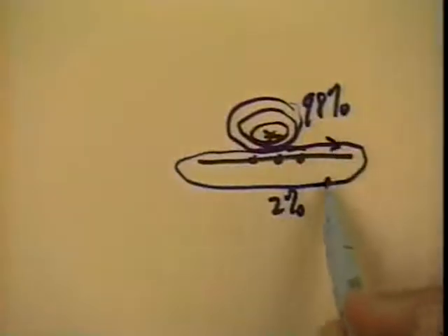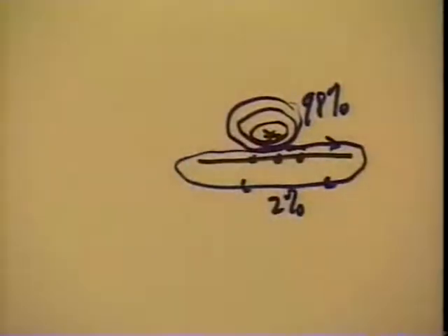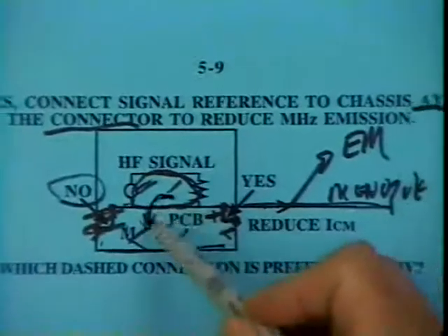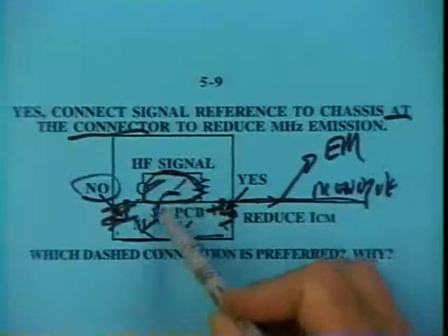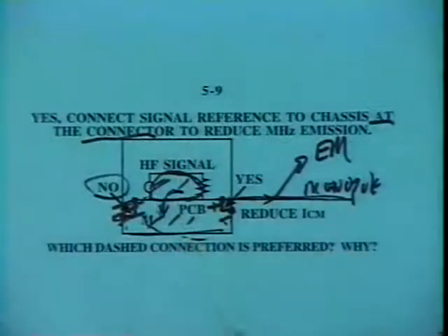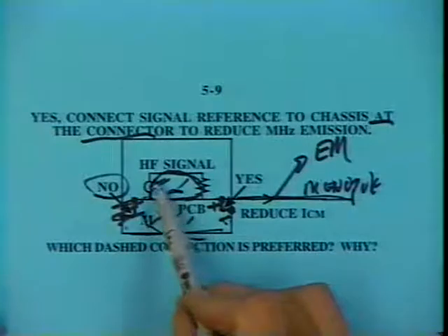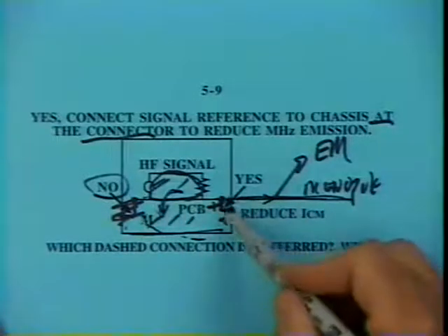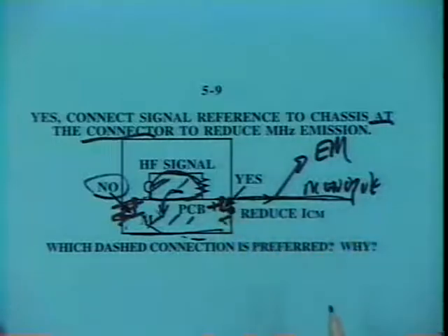Because this flux that wraps around the wide portion of the circuit board is exactly the flux that we're talking about in this picture here. That's what's wrapping from one loop into the other loop. We need a way to be able to control that. If we can control that, then we can diminish the coupling between the two circuits, the high-speed digital circuit and the antenna circuit. But of course, if we have the right connection for our circuit board, that can help us control the problem as well.